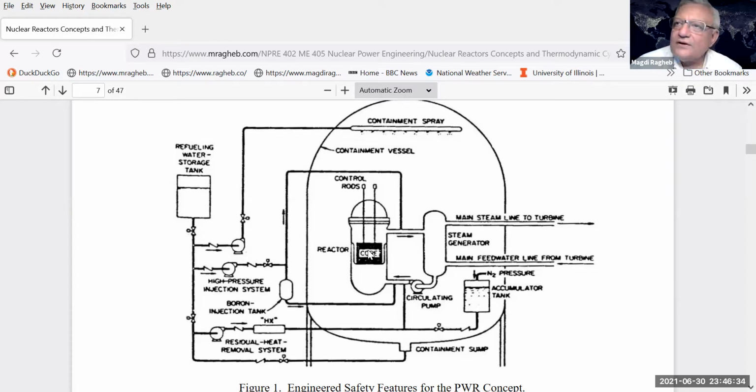And it's very different than when you operate, say, a boiler in a coal power plant. Once you stop injecting the fuel into the boiler, the production of energy ceases. But in nuclear reactors, you'll find that those fission products continue emitting radiation in the form of beta particles and gamma radiation. Initially, at time t equals 0, after you shut down a nuclear reactor, you are producing about 8% of the fission energy or power even after you shut it down.